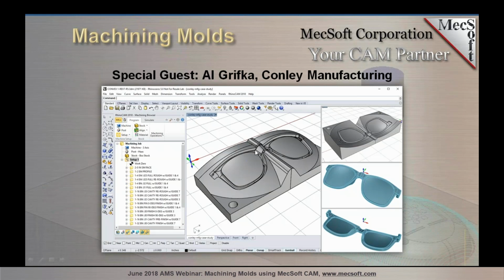And this is what RhinoCam was really good for. Say maybe one cutting operation doesn't quite meet your needs. There are multiple different cutting operations and parameters that you can set to really get down into the fine detail, making sure, especially in a mold, that your parting lines are really good, because in a mold, anything that is not quite correct is going to show up on your final part.